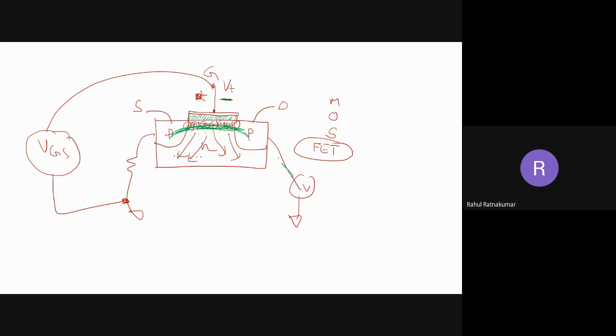So now, if I give a voltage, there is a current passing and I get output voltage here, right? This is the controlling mechanism of the P MOSFET, P-type MOSFET. So we have a negative voltage. Gate voltage is negative. You can see the gate voltage is negative in terms of P MOSFET. That means VGS is like this, whatever, or this can be zero, or this can be minus 2 volt, minus 3 volt, whatever.